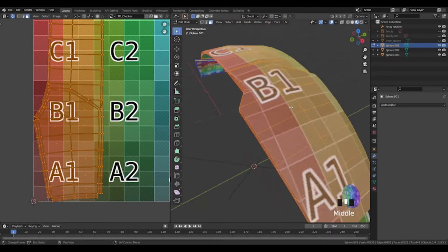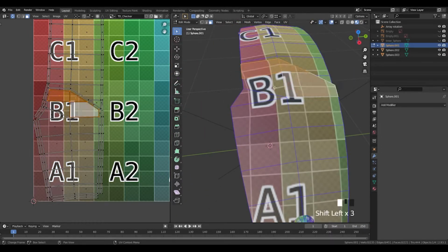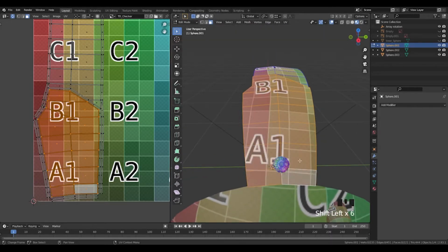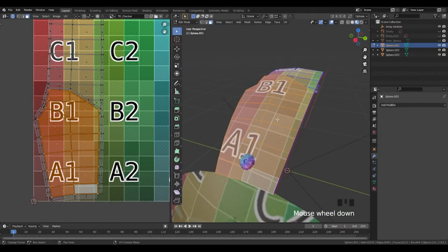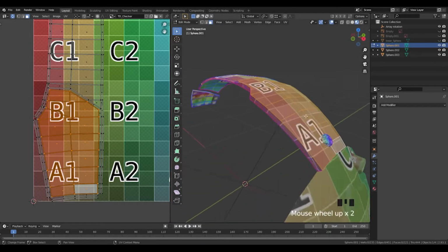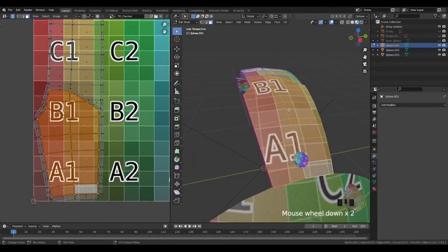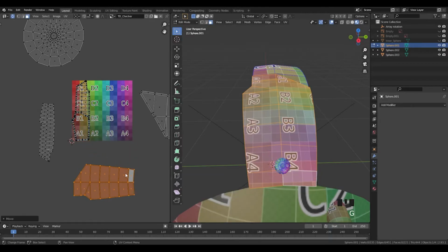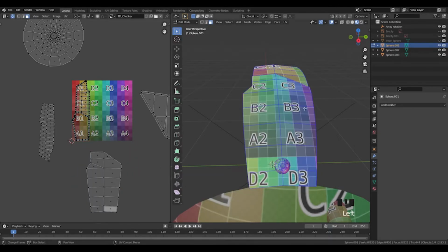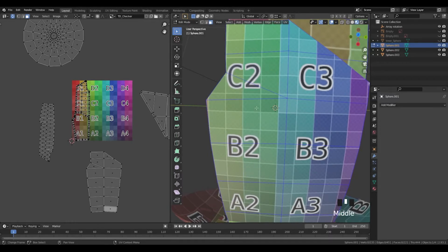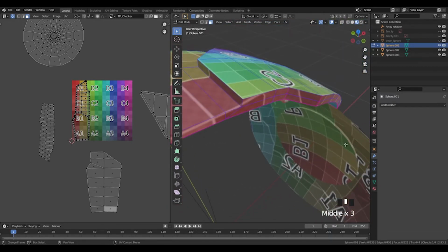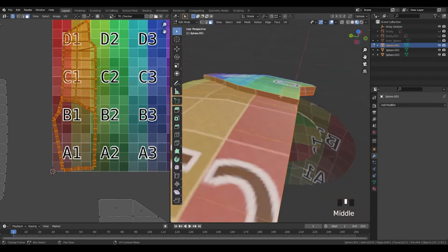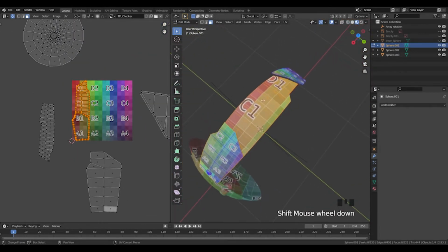I think what we'll do, because this section will eventually have a normal map applied to it to give it the textured look, we'll UV this separate and make it its own island, just so later on when we do apply that, we know it's gonna be nice and straight. Look at the top.